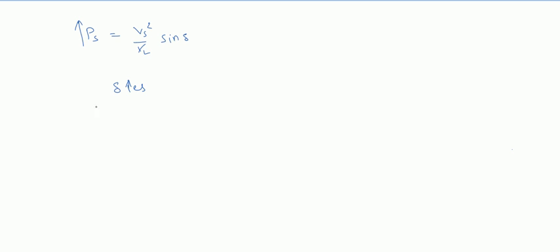But we cannot increase the value of delta above a certain limit because of stability concern. This delta value is limited to up to 50 to 55 degree.